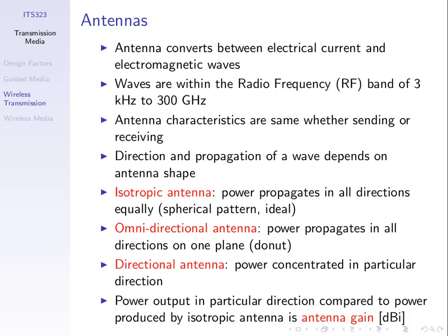One factor that we know about is attenuation. As that signal travels across a distance, it will get weaker and weaker. Today we'll cover how much weaker. So if this is my transmitter, I transmit with some power level, say 1 watt. The energy comes out. If this is an isotropic antenna, the energy goes in all directions. And at some distance ahead, if I measure the power at that point, it will be less than 1 watt, because it gets weaker across distance. We want to see the relationship between